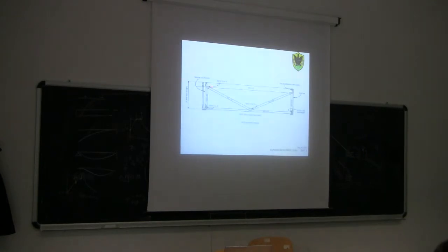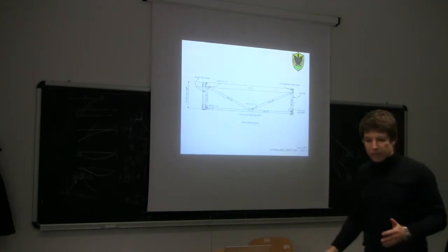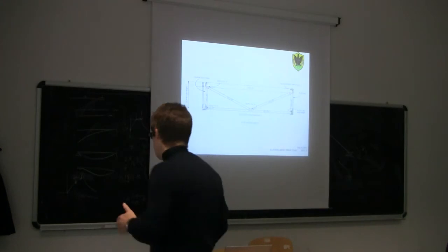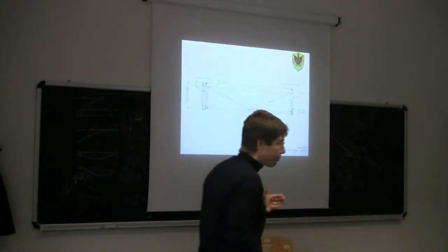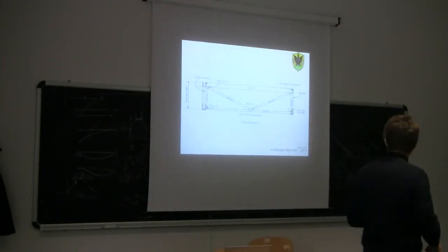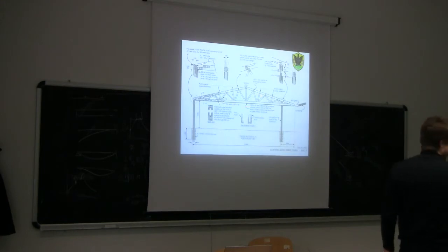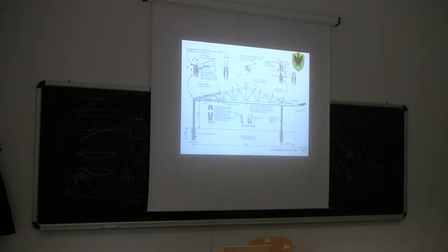And those truss systems have a very important function. The function of those systems is basically to prevent out-of-plane flexural buckling of those truss systems. The truss system may suffer from out-of-plane buckling, like beams.